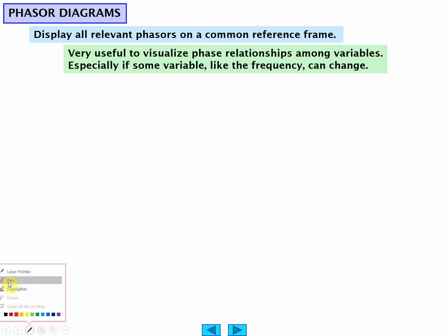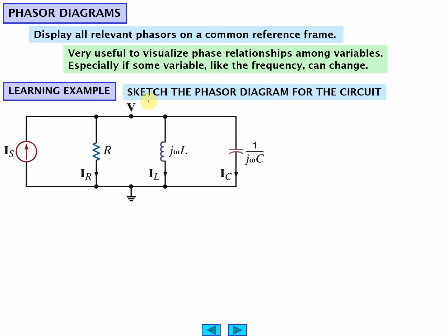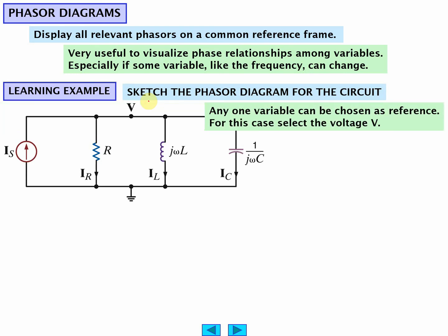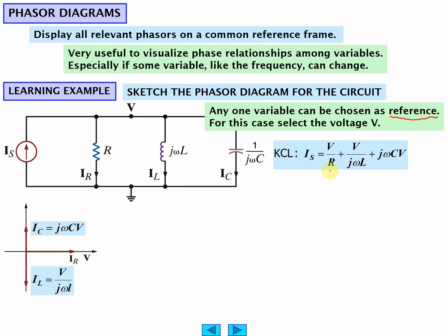Okay, you guys, we are going to talk about phasors now and the way to diagram them. So we've already got the notation. It's how do we make a diagram? And what you do is you select a variable as a reference. So that will go along the x-axis. You could make the current the reference. And here's how you draw that. This is the diagram right here.